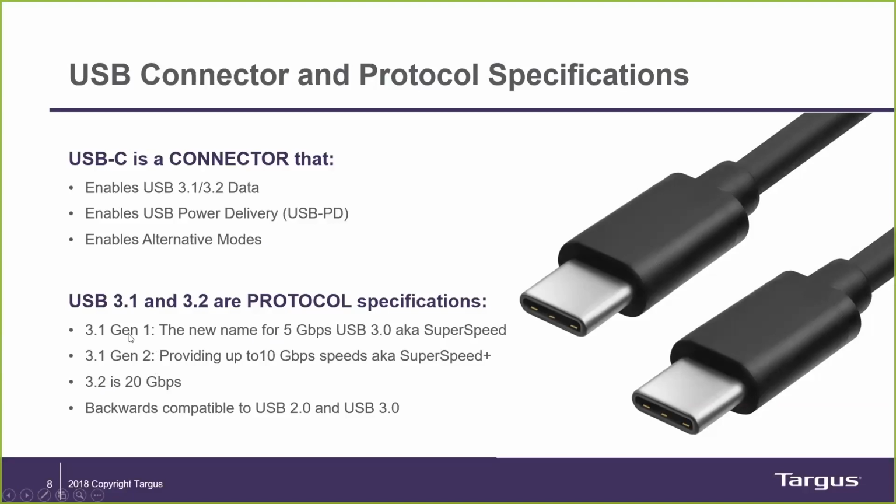So these are very different things. There they are in summary, very different protocols. The good news is they are all backward compatible. All right. The other thing that gets confused a lot is people assume that this connector is USB 3.1, or they'll call it USB 3.1 connector. It's not the USB 3.1 connector. It's the USB Type-C connector.